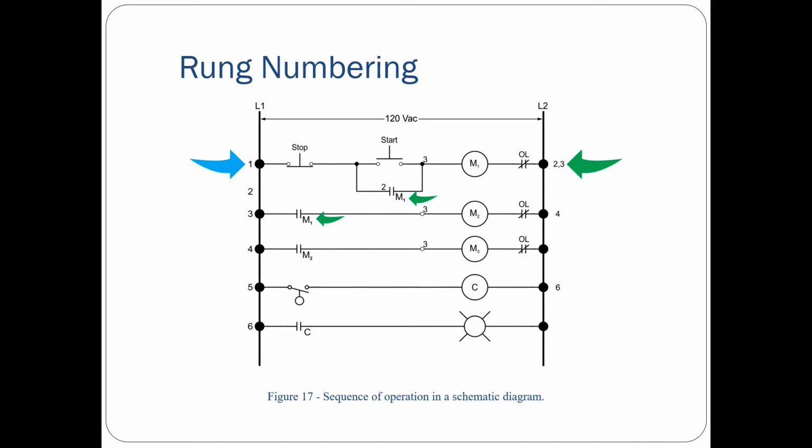This way we can go through the drawing, identify the contacts that are related to any one coil, and we know what's going to operate next. This helps us with our troubleshooting and our order of operations.